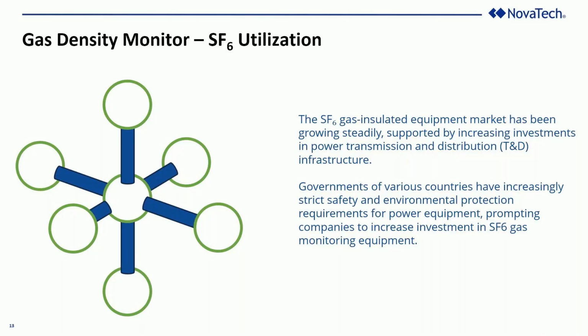It is driven by the demand to have more compact and reliable high voltage solutions. You can actually have a whole SF6 gas substation, called a GIS substation, that reduces the footprint, I think, by, and I could be wrong, I don't have this in my notes, I think it reduces it by like 75%.